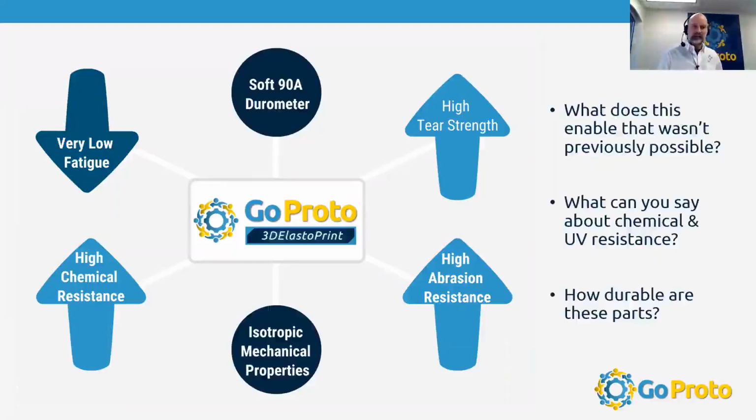And that's always tripped us up in the prototype phase. Like, well, I can get you a printed photopolymer that's going to feel kind of gummy, sort of weird, certainly not cosmetic, or I can make you cast urethane, which is a great process. You make a silicone rubber tool from a master pattern, remove the master pattern, then you have a tool that you can make multiple parts from. We can vary the durometer, we can vary the color, we can do overmolding, a lot of really cool things, but it is still a urethane-based material that who knows what's really going to happen when it gets cold or hot or sits in the sun for 3 weeks while you're doing your testing, or it's going to vary around a lot.